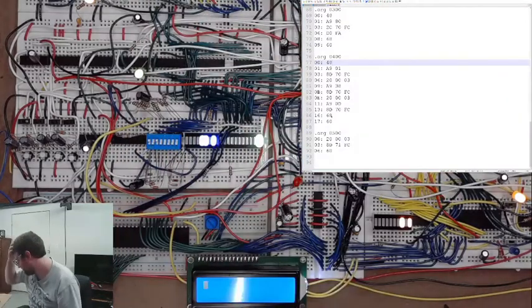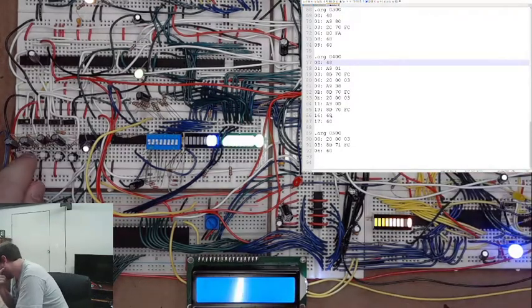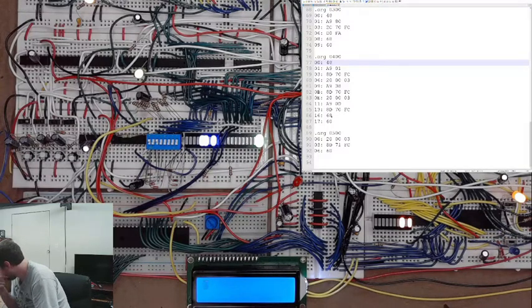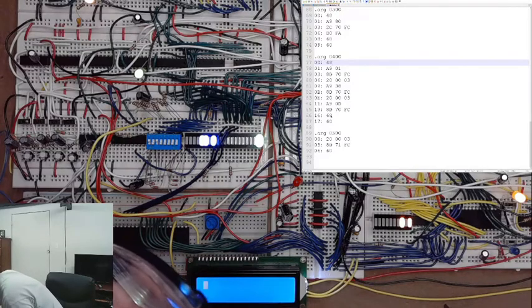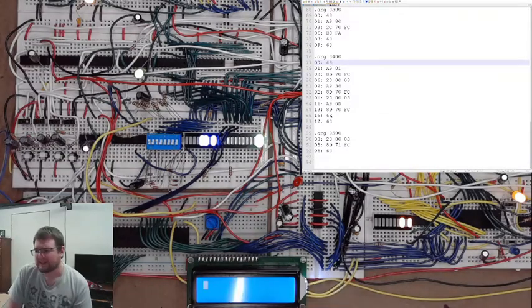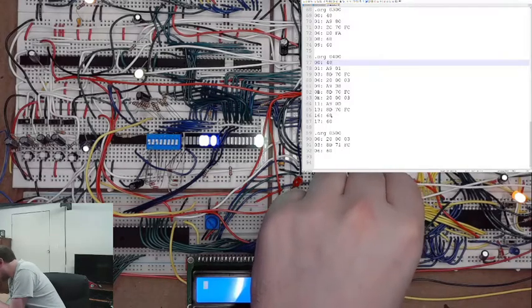Okay, and it does come over here. So if we reset, this should go high. And there it went low for some reason. Oh, I guess I need to either go look at that chip or just permanently tie this pin high that it goes to. Or